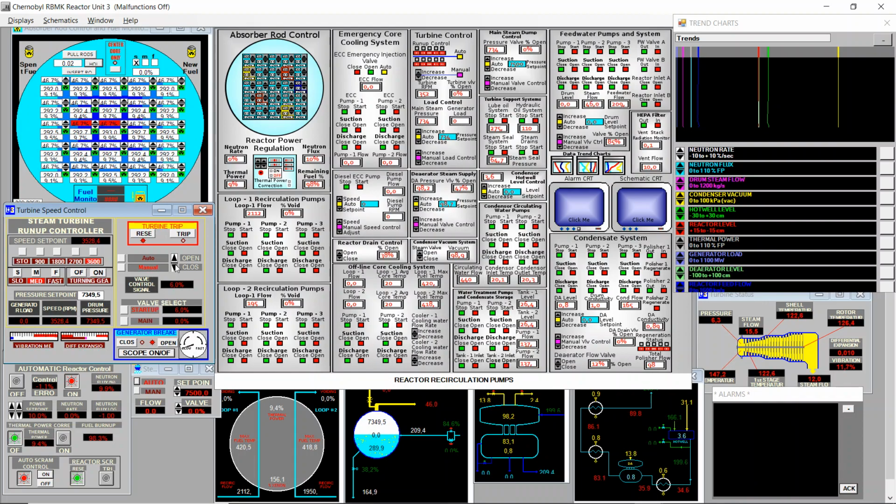Okay, we are getting closer to nominal velocity, so I'm just around 1% of opening above what we need for the nominal. So we see the increase of speed is slower and slower. Now it's increasing just 2 RPMs per second, more or less. When we reach 3590, I will decrease 1 point more, so 0.5%.